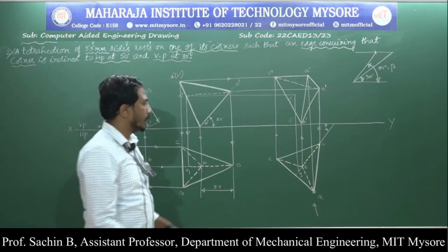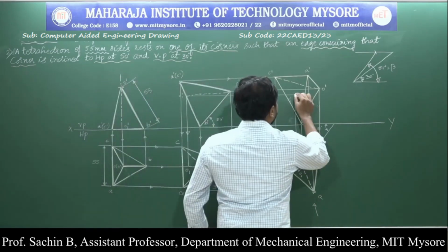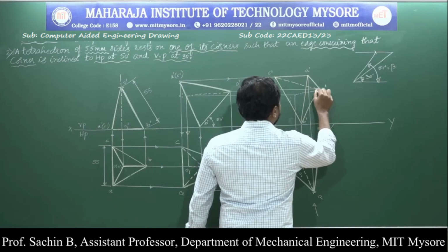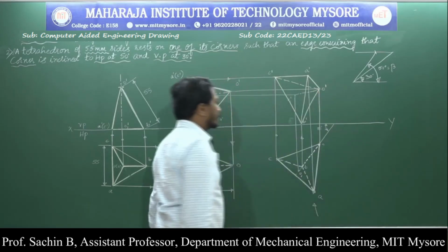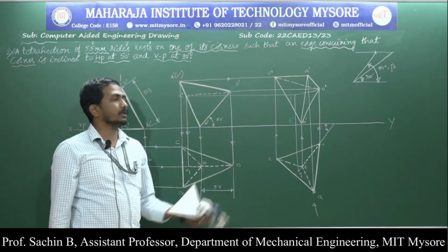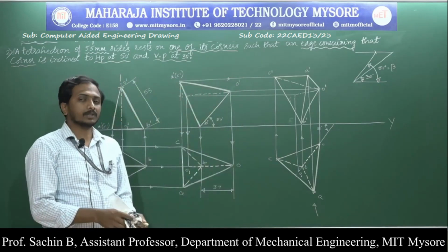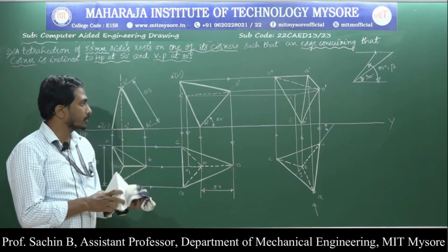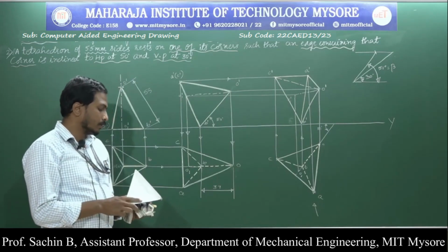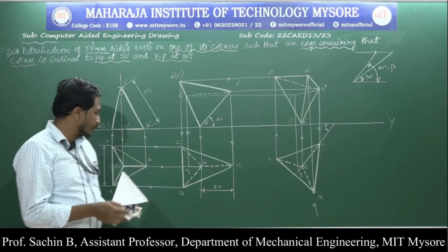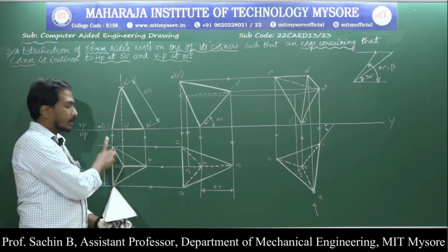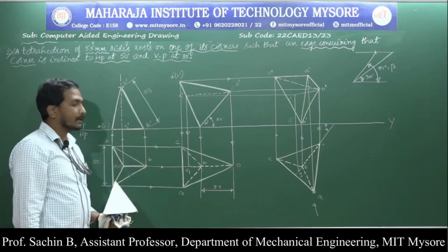Next, I will go for drawing the axis. Okay, this is my last position of the object when it comes to the tetrahedron. In the tetrahedron, they are going to give the length as 55 mm. Don't get confused. Construct an equilateral triangle of 55 mm length.